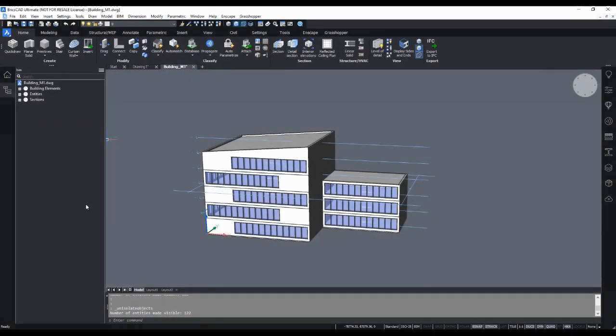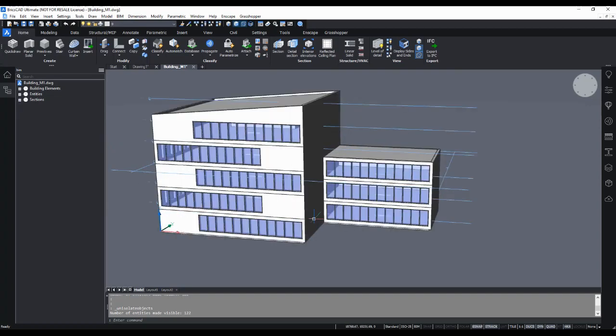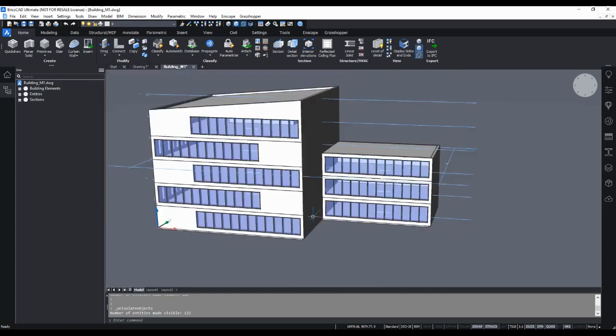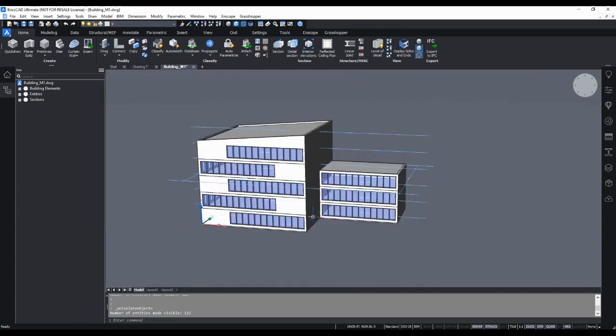As you navigate around and through your 3D model, the location of the model in space remains constant. It's just your current view or your viewpoint of the model that's changing. So let's talk a little bit about how you can navigate. The most used navigation tools are zoom in and out, pan, and orbit. And these can all be easily accessed through the mouse and keyboard. To zoom in and out, you just use your middle button or your scroll button on your mouse, and that will very easily zoom.